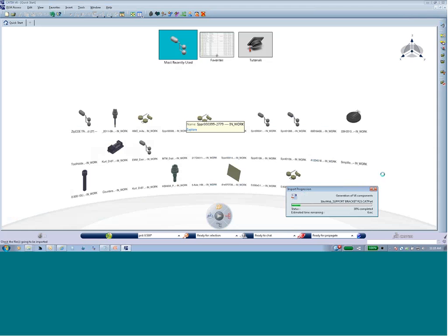Now there are other options available. There are mapping tables that will allow it to look to see if any of the data was previously imported. Remember the tool structure that we just looked at. Any of the V5 tools that are defined simply as parameters inside of the V5 NC program are now going to be assemblies with other parts in V6.